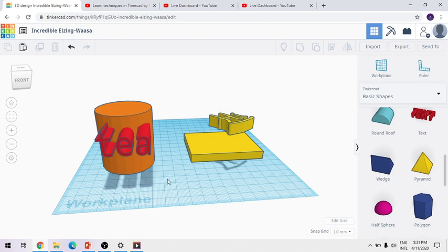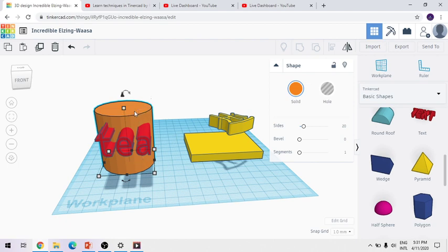Next, you have to duplicate this object. Okay, so for duplication there is one shortcut, Control D, that duplicates the object. So what is the difference between copy paste and duplicate? Copy paste will paste the object at some other position, with some distance, and the duplicate option will duplicate the object at the same position.